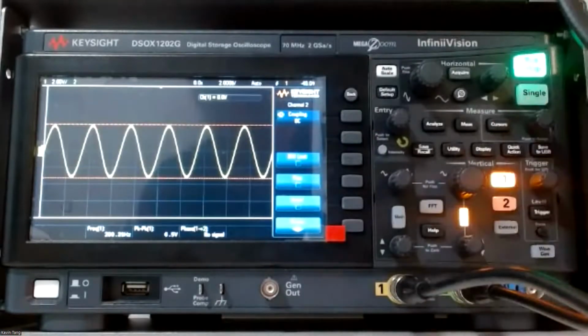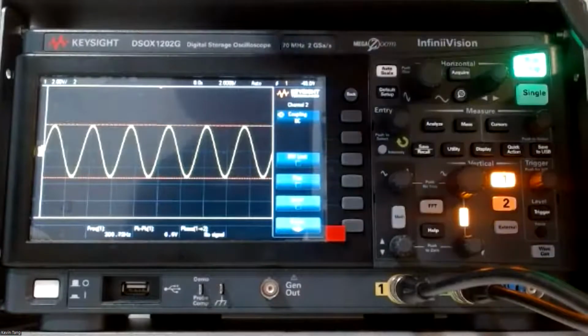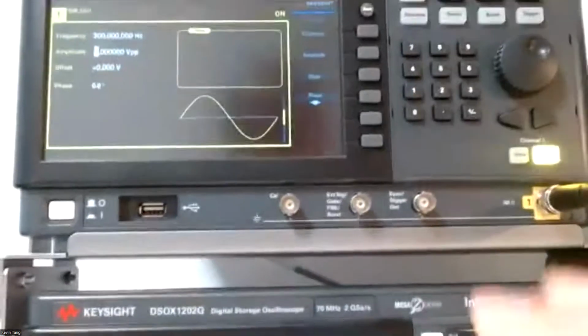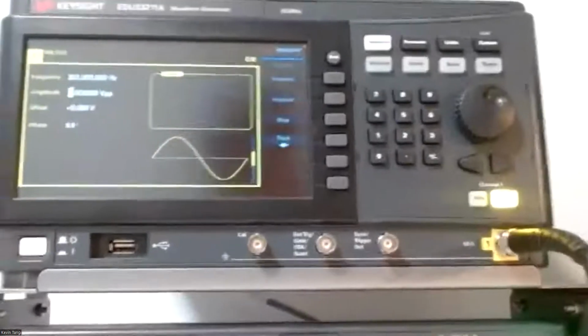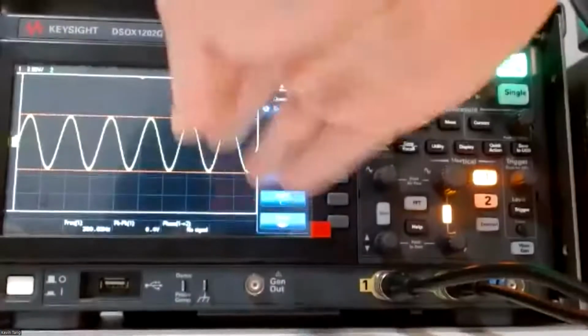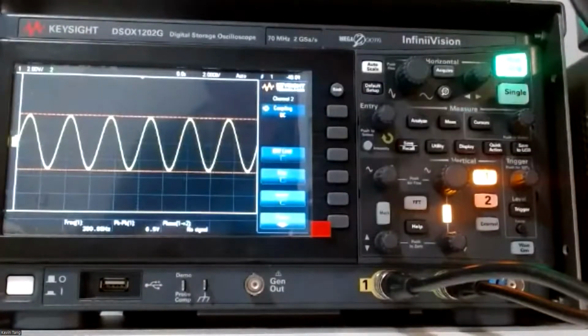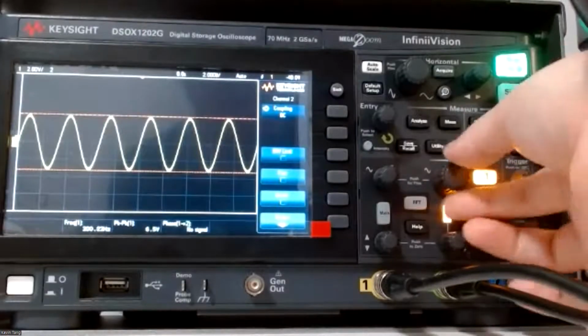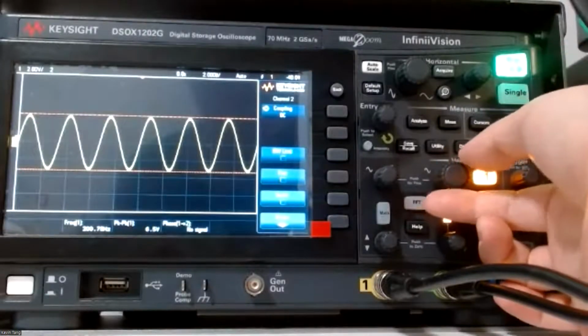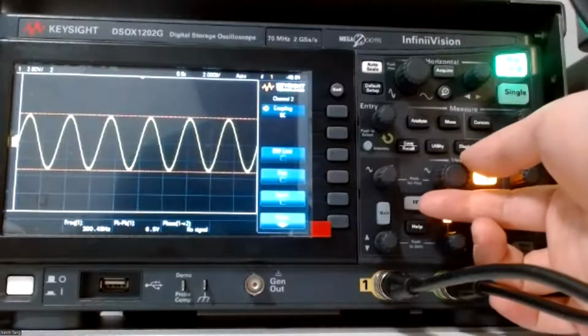The only way you can change the wave itself is to change the function generator. So if you wanted to go up and down, in a real case, you're using DC offset. But this is not really providing a DC offset, it just changes the position. I hope everyone understands this, right? Because I see some students get confused about this even when they get to third year.